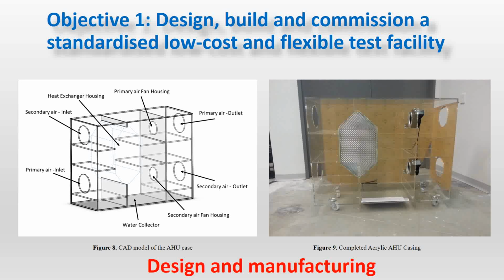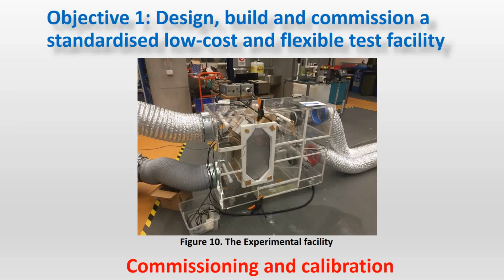Finish the thing, put all the measurement equipment, the 4 stations, 1, 2, 3, 4, as you saw in the previous schematic diagram, connected to a system where we can simply modify the air temperature and humidity to a certain level. The water pump is sitting here somewhere in the back, the 2 fans. As you can see, this will be the return air entry going through the heat exchanger, and this is the exhaust air, red color. The hot air, which has been made up by the machine, is going to be passing through the dry channel, and we're going to have the supply air.